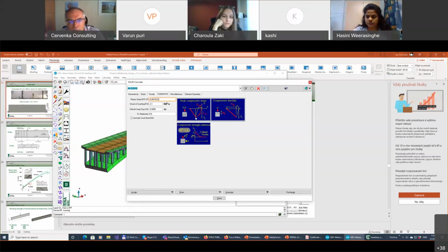If you make a loading test of concrete in compression, then you can easily determine the strain at the peak. And if you subtract the elastic strain at the peak, you get this epsilon CP. This is one of the input parameters in ATENA. I again emphasize that it is only the plastic part of the strain at the peak, not the whole strain. But you can easily calculate that, and it has a clear physical meaning.